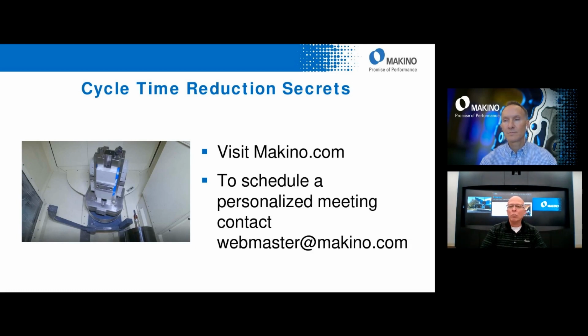So obviously you start with what material you're tapping and what material is the tap. It starts there with your surface footage for that particular tap, and you calculate the RPM based off of those inputs. One thing I do want to point out is rigid tapping RPM, there's a limit to that on each different machine platform. For example, on the A51, I believe the max rigid tap with the standard spindle is 2,800 RPM. With the 20K spindle, it's 4,400 RPM. So based on your RPM and your pitch size, you calculate your feed, and that's your max tapping feed. Now that is also the max retract.